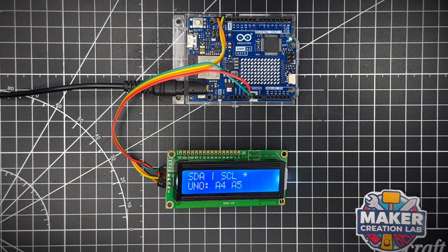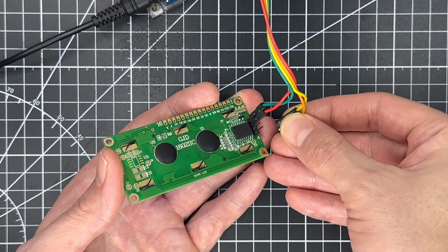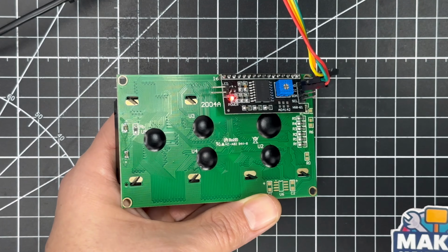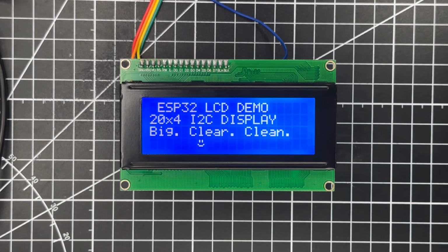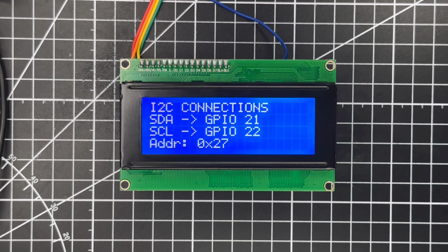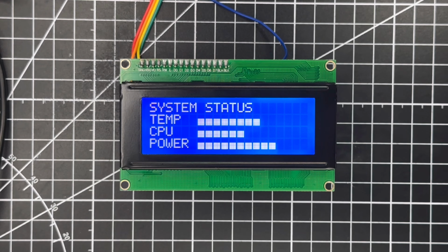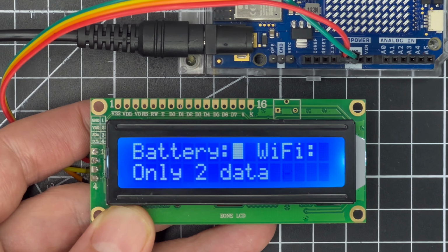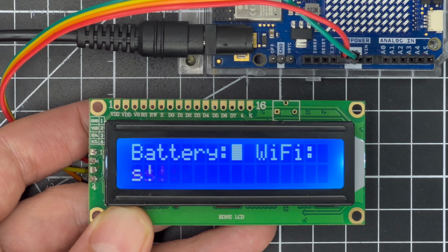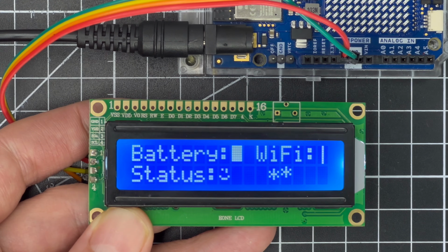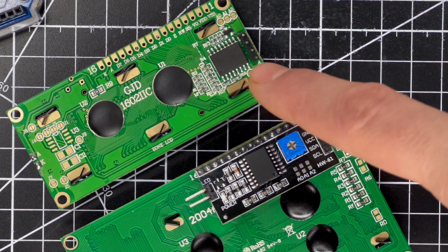This is the most common Arduino display and probably the easiest to implement. It runs on the I2C bus, which only requires 2 signal cables, serial clock, and serial data. This is a character display, making it perfect for displaying text, menus, score counters, and system status screens. If you're just getting started, this is definitely a great choice. Make sure you grab one with a built-in I2C driver chip.